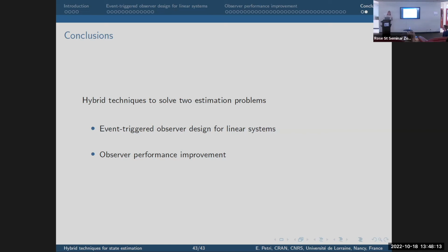So we are actually having the observer in open loop without a correction term. And thanks to the reset, every time there is a switching, the initial condition of the continuous-time part is kind of reset. So we are improving all the modes. The one with a gain equal to 0 was not converging, but was not diverging because it has an eigenvalue equal to 0. And if we reset it to a smaller error, thanks to the information given from the others, this reduces the error.